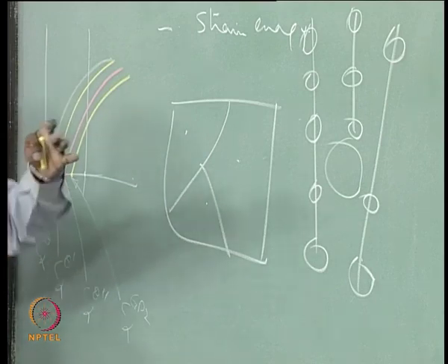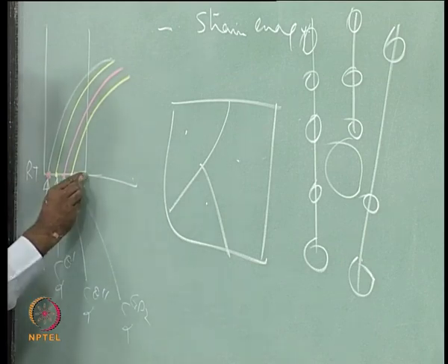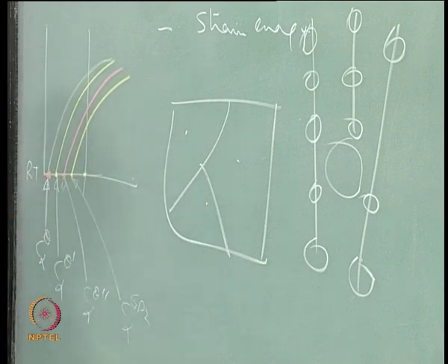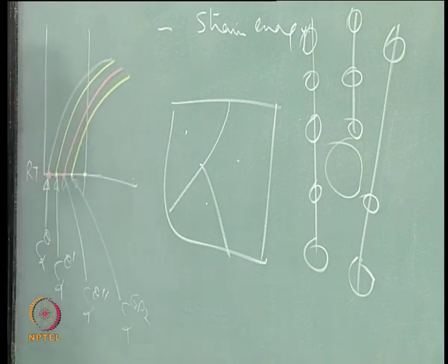And now if you look at this particular solvus and carefully observe what I have been just saying in answer to Anisha's question, if I take this alloy and bring it to this temperature, at this temperature this alloy is below the solvus line for all 4 of them. When does a precipitation take place? Whenever my alloy composition comes below a solvus, then only precipitation happens.